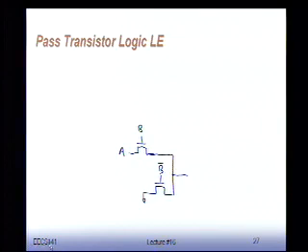Because remember, logical effort is you look at the input capacitance, assuming that you have the same driving strength. So now we have to figure out what is the driving strength of this thing. That's pretty tough to figure out. If you look at input A, we have to compare how fast this thing would work.